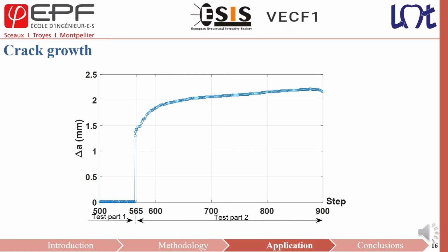Despite small displacement levels, it is observed that the FE procedure identified small crack lengths. These results show that this method makes it possible to measure very small crack growth even with a very low level of deformation. This crack extension law is taken into account to calculate the J integral, but only the second part of the test is studied.